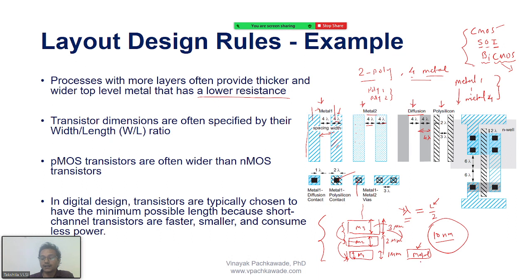because that will offer the resistance of the wire, rho L over A. So if I have a larger A, where A is width times thickness, if I have larger width and larger thickness, the resistance is coming down. You know that. Yes, sir. See, M2 has a lower resistance compared to M1.